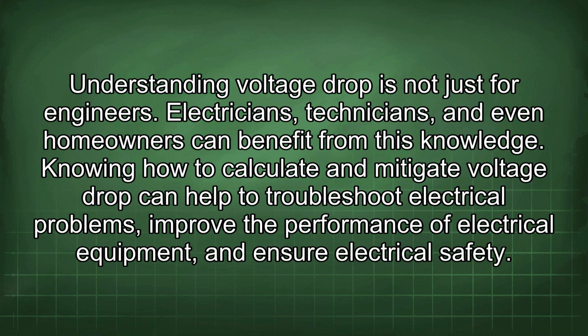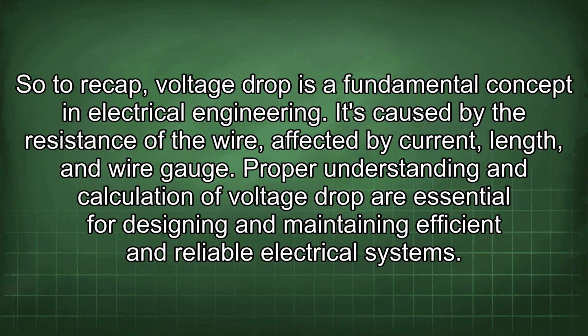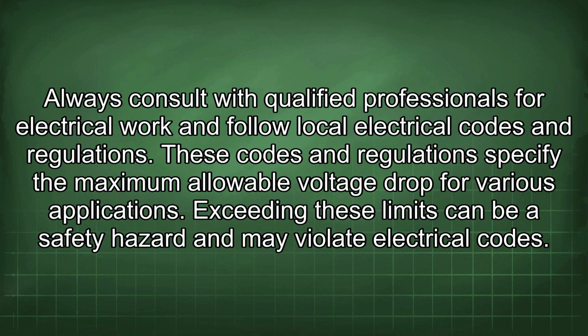and ensure electrical safety. So to recap, voltage drop is a fundamental concept in electrical engineering. It's caused by the resistance of the wire, affected by current, length, and wire gauge. Proper understanding and calculation of voltage drop are essential for designing and maintaining efficient and reliable electrical systems. Always consult with qualified professionals for electrical work and follow local electrical codes and regulations. These codes and regulations specify the maximum allowable voltage drop for various applications. Exceeding these limits can be a safety hazard and may violate electrical codes.